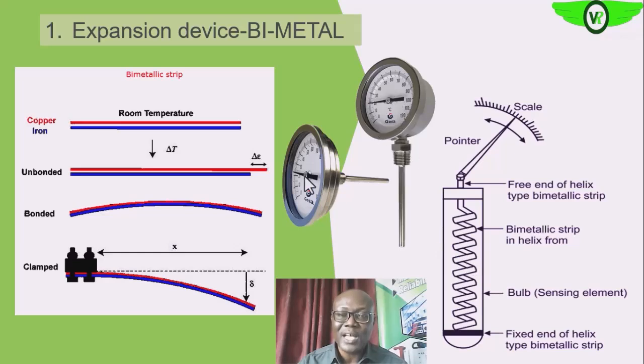So these are examples of the thermometer gauge, temperature gauges with the bimetal that is in this sensor, or in this area that is attached directly, okay, into the process. So here I have a direct contact with our process. As it's heated up, the bimetal in it will elongate, and that will cause the movement of the temperature gauge.